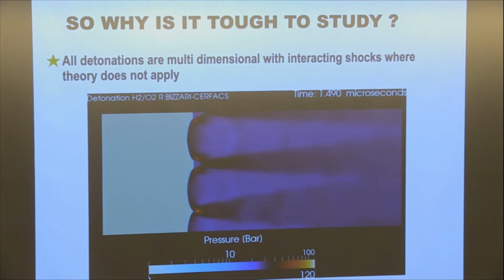The results get worse. You don't get the right size, you don't get the right speeds. The structure is not as good as the one which you have with a single step. Of course, it's not really fair because the full scheme, you don't tune it, while the single step, you tune it until you find what you like. But still, most people computing detonations, they don't want to go to too complex schemes.